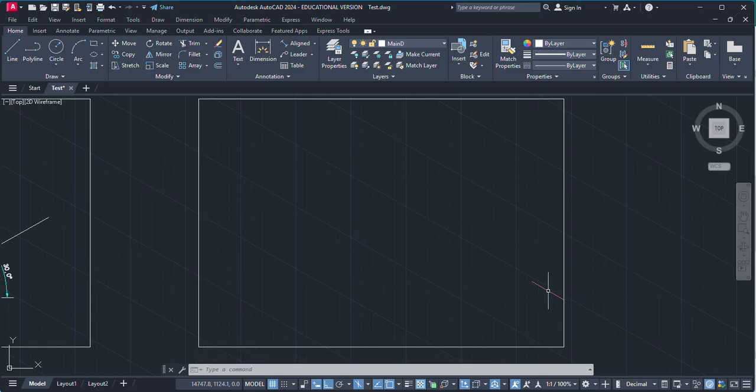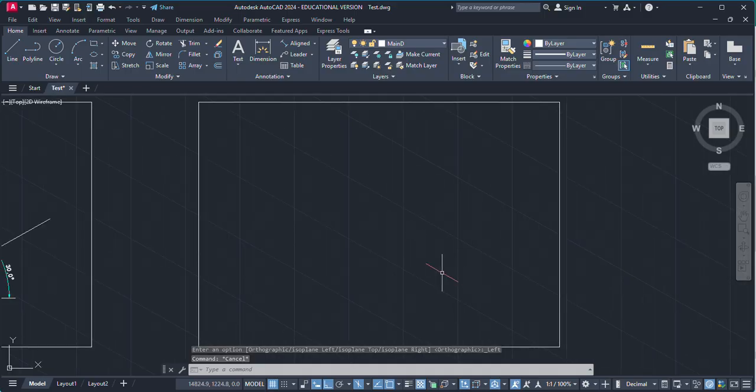This whole sheet or whole grid is inclined at some angle. If you scroll to the right of this isometric drafting, there are three planes: iso left, iso top, and iso right. Initially iso left is selected, so all the grid lines are at certain angles. If I make it iso right, the rotation will be in the opposite direction.